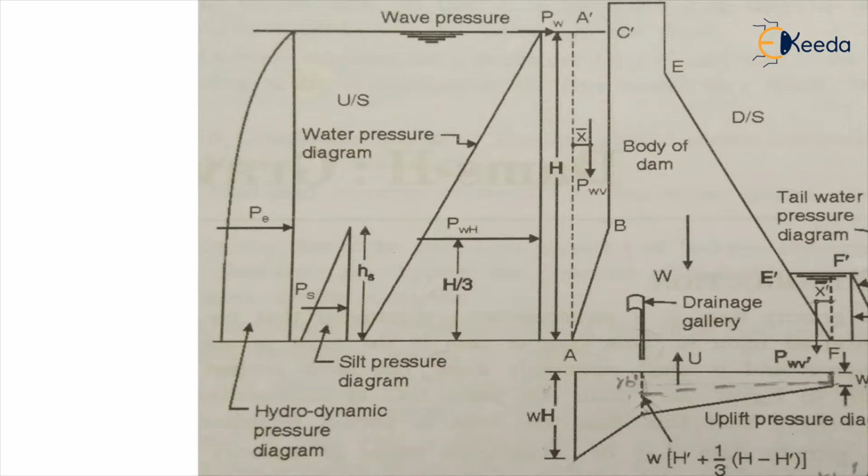So when this force exerts pressure along with the water in a horizontal manner, it is known as hydrodynamic. See, dynamic means the pressure exerted along with the forces. Kinematic means the forces along with the motion only, it does not consider the forces. And static means it keeps it in a rest position. We had already studied these three phases in fluid mechanics also. So we have to take this hydrodynamic pressure into consideration, because this is the most important factor categorized under the earthquake pressure.